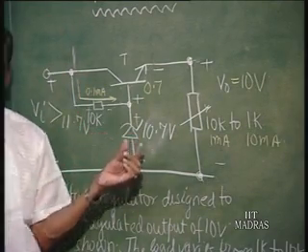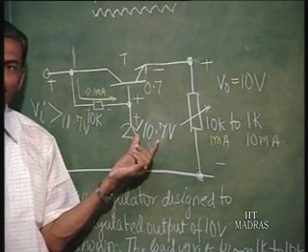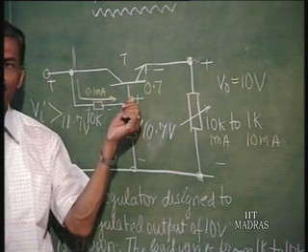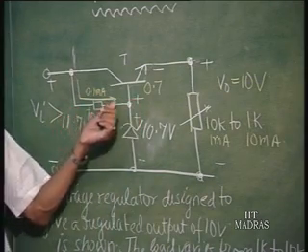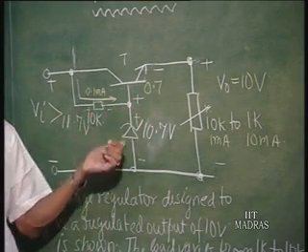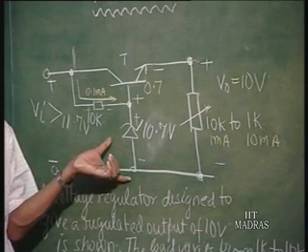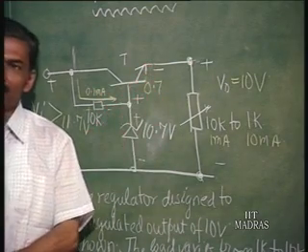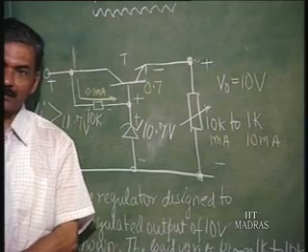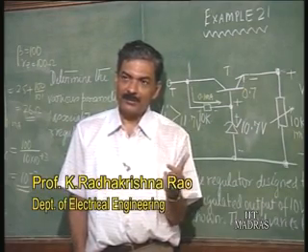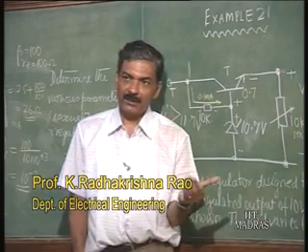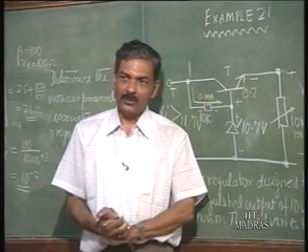So, then also base current is going to change divided by beta. As this base current changes, you can establish how much the Zener current is going to change and find out delta Z. So, that will give us the load regulation factor. Again, find out delta V naught divided by V naught, expressed as a percentage, it will give us the load regulation factor.